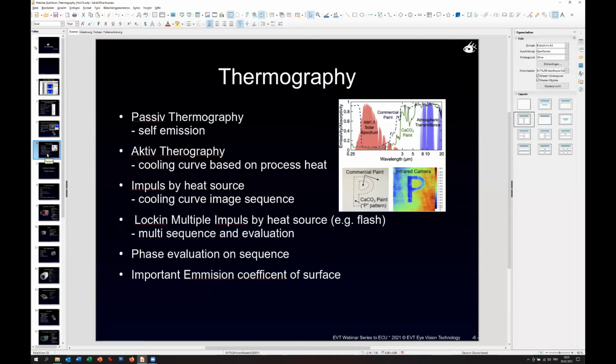but in most cases the problem is because as a human eye, you look at this part, you will realize there is no reflection, of course. But in reality, the heat wavelengths are reflected from this part. So sometimes you see yourself as a heat spot on that surface, because the heat is reflected even from that surface, or any other heat source which is within the field of view.